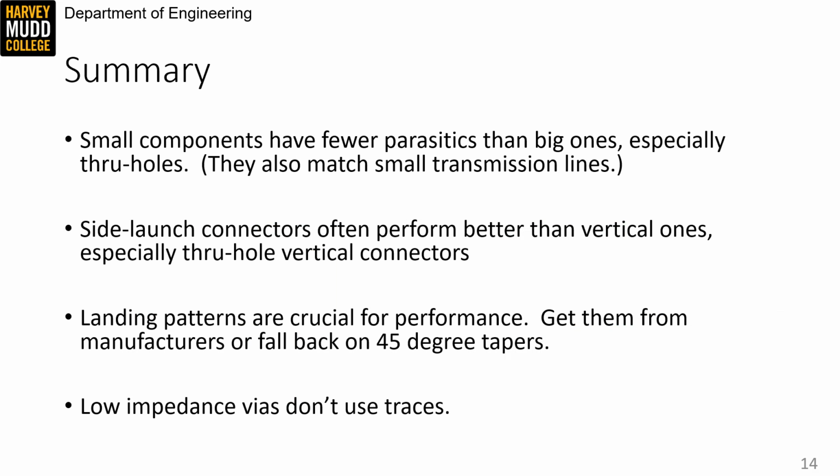So in summary, small components have fewer parasitics than big ones, and small components especially have fewer parasitics than through holes. Side launch connectors often perform better than vertical connectors, especially through-hole vertical connectors. Landing patterns are really crucial for performance, so make sure you get them from manufacturers or fall back on 45-degree tapers. And low impedance vias won't be connected by traces, they'll just be merged directly into pads.